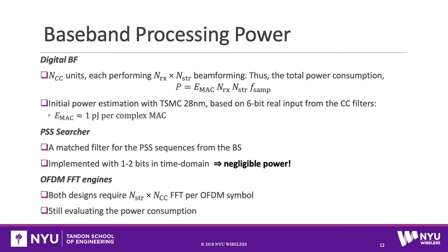The fully digital beamforming design also requires a linear digital beamformer which multiplies the inputs from the NRX antennas to NSTR digital streams. In each sample, it must perform NRX times NSTR MACs.